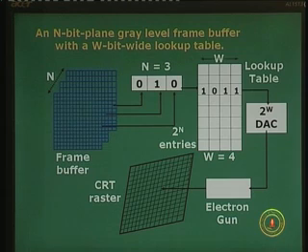and the lookup table output goes to 2 to the power w DAC, and the DAC gives a corresponding analog voltage intensity, let us say, which is proportional to the input to the DAC. So out of 16 possible values, although he gets in 8, it has the capacity to give any output from 0 to 15, although there are 8 possible values. So, electron gun, of course, the CRT, the rest part of it is very simple. So, this is a typical arrangement.